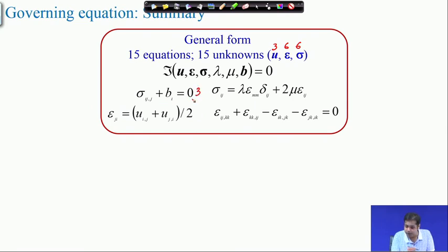We have 3 equilibrium equations, 6 constitutive relations, and 6 strain displacement relations, or compatibility equations. So, the total relations available are 15.